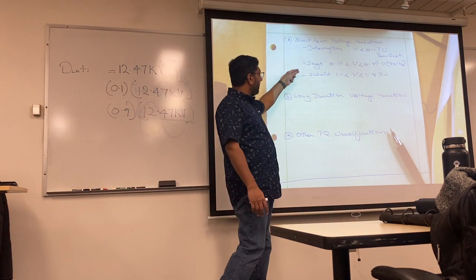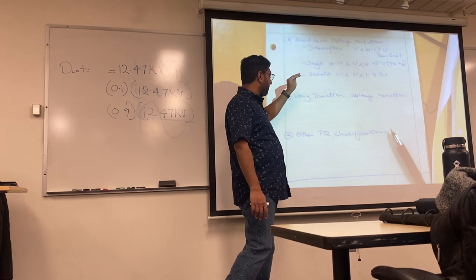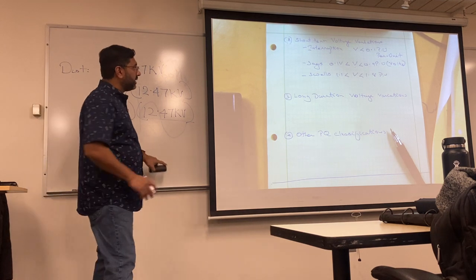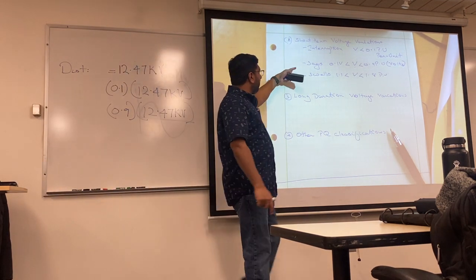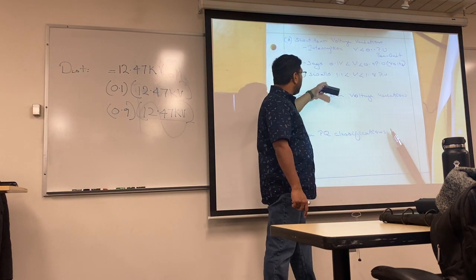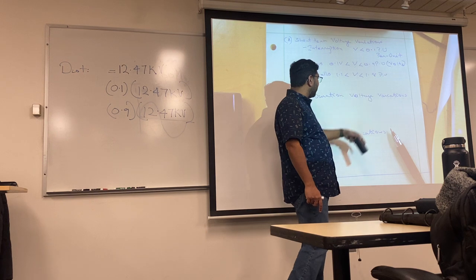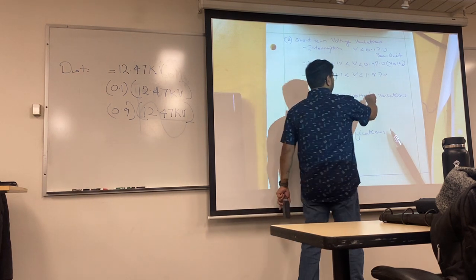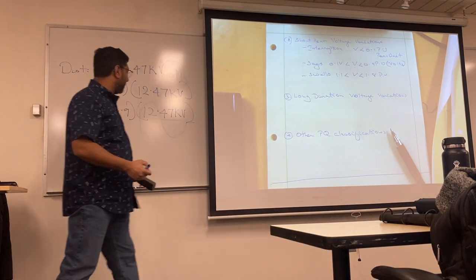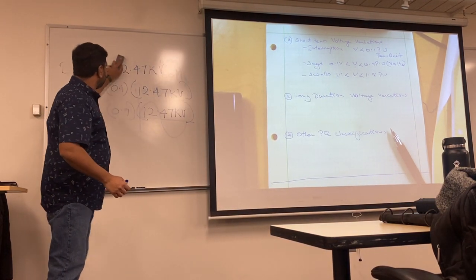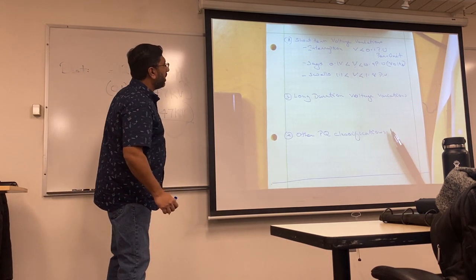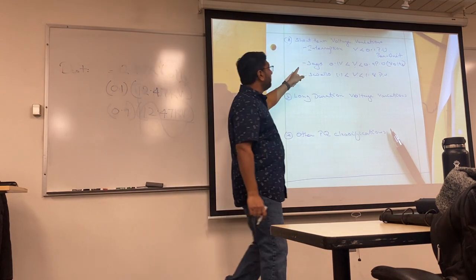Safe to say, even with this, we have ways and methods to make sure that you guys get your 120 volt, but there is a lot of stuff that's happening in between. So sag is when you are operating less than the assigned voltage. Swell is when you are operating more than the assigned voltage. Truth be told, if you are doing 1.8, we'd rather shut down the system and figure out what's happening. So in an interruption, there would be 0 voltage, right? That implies it's disconnected or turned off. So, short-term voltage variations.